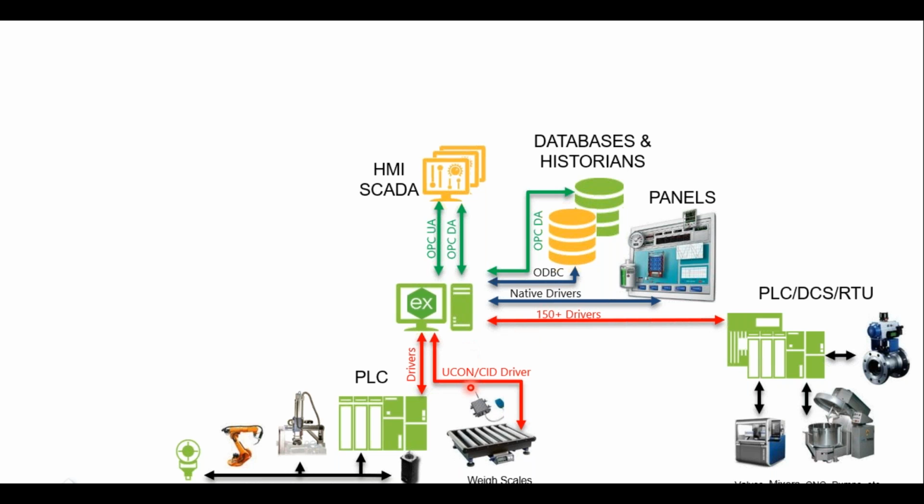There is a specific driver called the UCON driver, which is a user configurable driver. There are some devices in the plant like weighing scales, RFID, barcode readers, which do not communicate on a standard protocol like Modbus or Profibus. For that we can even write our own driver. Of course, it involves engineering effort, but there is a provision in Kepware that you can build your own driver. Typically it is for serial devices where we don't have standard drivers.